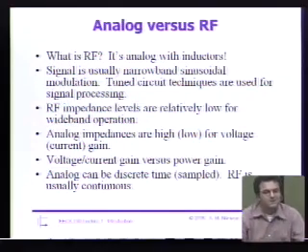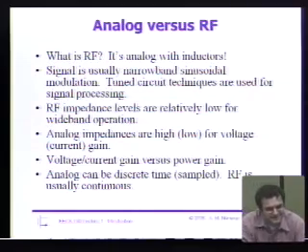Debo, why do we use low impedances? Better power handling capacity. Okay, that's a good point. If you look at transmission lines, for instance, and how much insertion loss you get, it turns out it's better to use impedances around roughly 50 ohms. The other answer, which I've written on the slide, is wideband operation. The lower the impedances you use, the smaller your RC time constants are going to be. And since RF signals often interface with the external world, where you have lots of capacitance, it's nice to use low impedances for that reason.